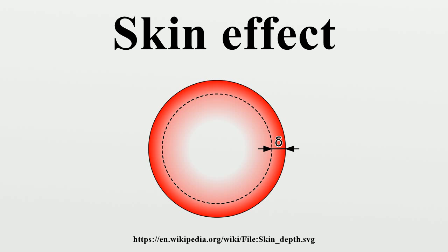Although the term skin effect is most often associated with applications involving transmission of electric currents, the skin depth also describes the exponential decay of the electric and magnetic fields, as well as the density of induced currents inside a bulk material when a plane wave impinges on it at normal incidence.